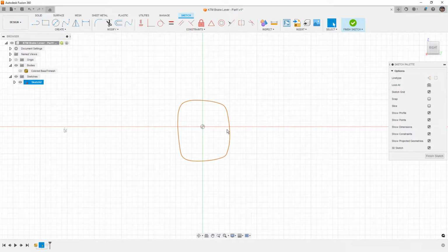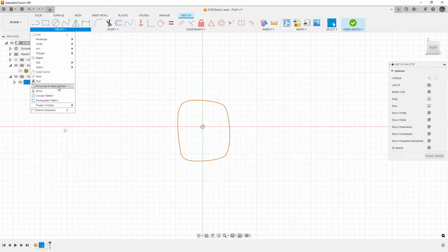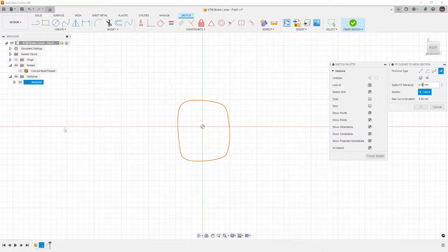So that brings me to the point of the mesh. Do we want to remesh? No, not really. Generally, if we're trying to get these curves, what we're going to be doing is bringing in a very high density mesh. And this is awful for performance. This mesh, it's a pretty small part, so it's not that big of a deal. But if you are bringing in a gigantic mesh with millions of triangles, then you're going to start to see performance issues. Here, it's not really making much of a difference, but in general, it would.